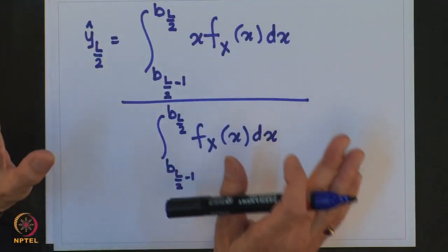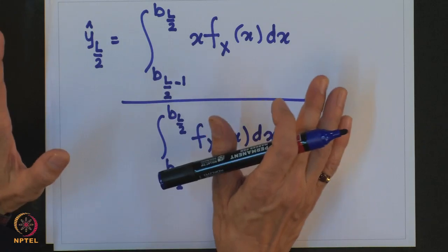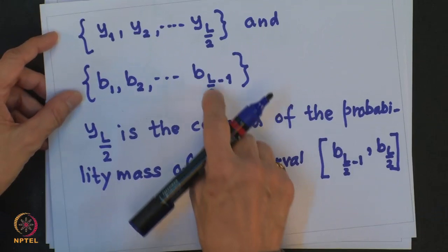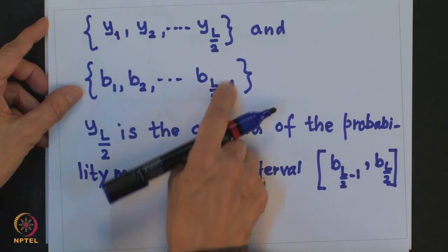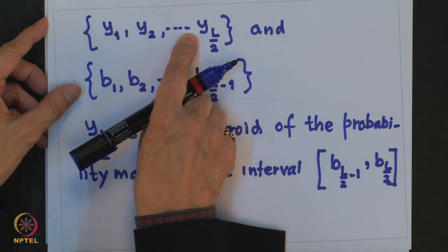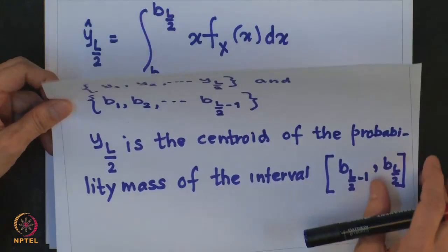If the difference is less than some tolerance threshold, we can stop, otherwise you will have to change the estimate of y1, that is your initial estimate, in the direction indicated by the sign of the difference between what you have got here and what you have obtained using this boundary point and the earlier reconstruction level, and then you repeat the procedure.